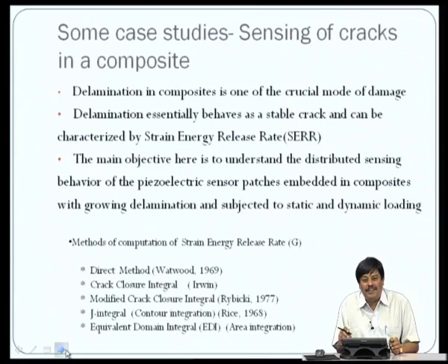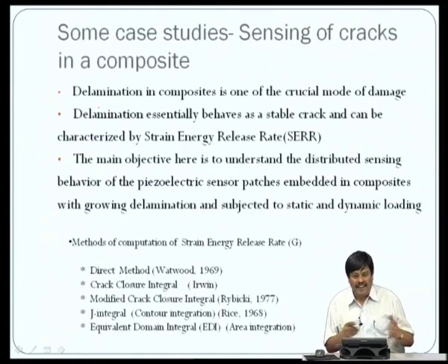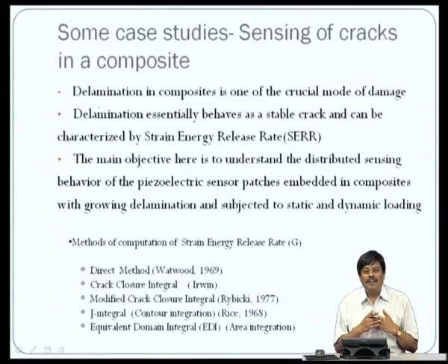What happens when the piezoelectric material is put on a cracked beam? Here we have taken a composite beam where the crack is in the form of delamination. Composite is constructed as a laminate, and due to excessive loading the laminate can peel off, causing delamination.